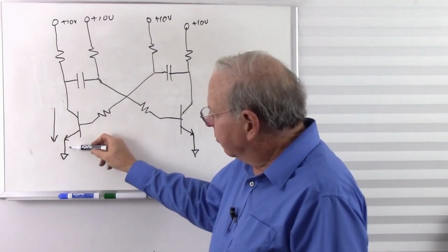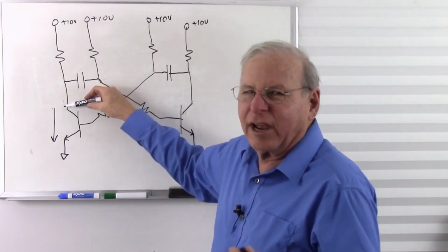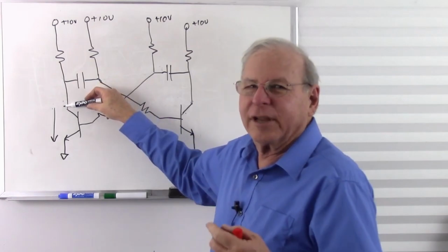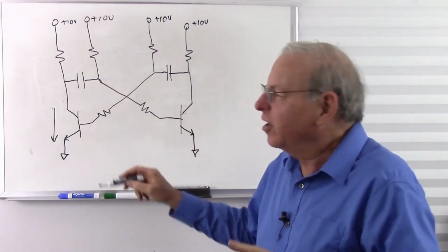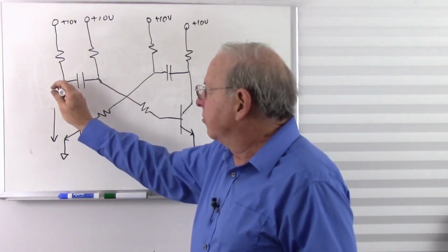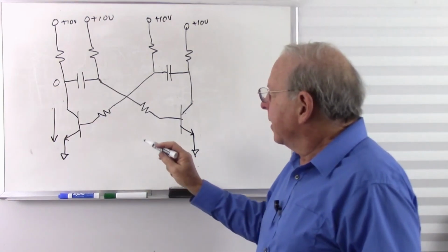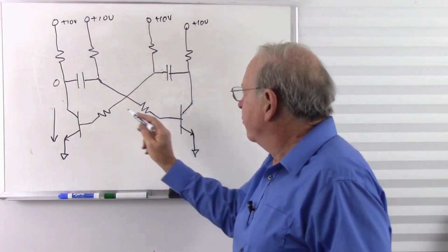So what's the voltage here? 0 volts. Closed switch, it's a short circuit. Basically, we have 0 volts here. Now it's a transistor. We're going to have something like 0.4 of a volt, but let's just ignore the saturation voltages and all the complications and just assume that looks like a closed switch. We can do that. So this is going to be essentially 0 volts there. And this capacitor is going to start charging towards 10 volts.